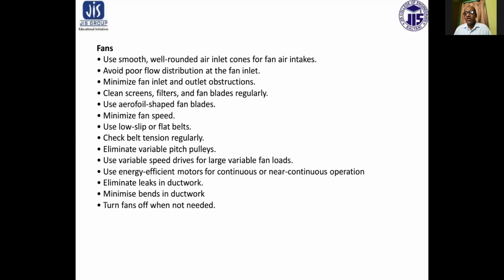Use aerofoil shaped fan blades. Minimize fan speed. Use low slip or flat belts. Check belt tension regularly. Eliminate variable pitch pulleys. Use variable speed drives for large variable fan loads.